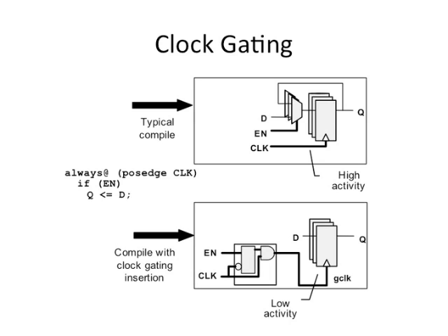The clock input of each flop presents a capacitance to the clock net, and you could easily have 500,000 or 1,000,000 flops in your chip, spread out uniformly all across the chip. So the clock net has to connect all across the chip, and there is a lot of wiring capacitance also associated with it.